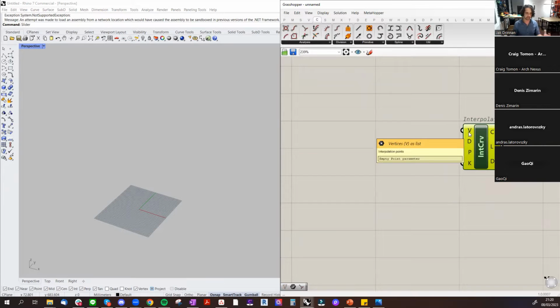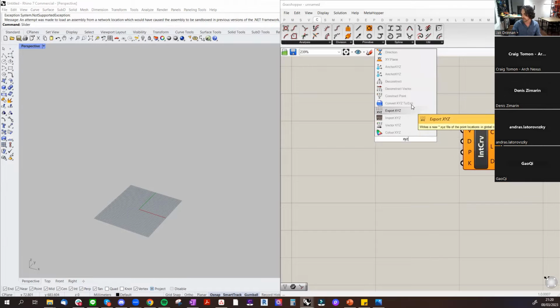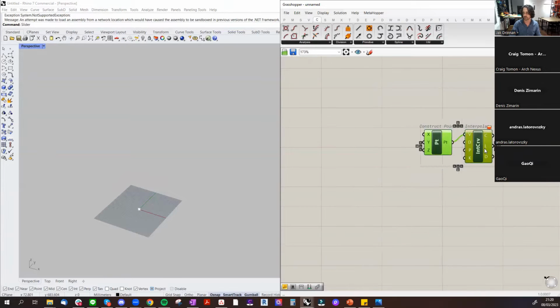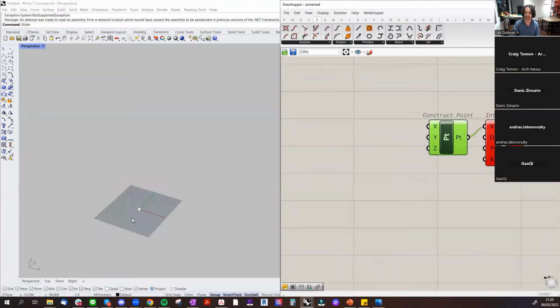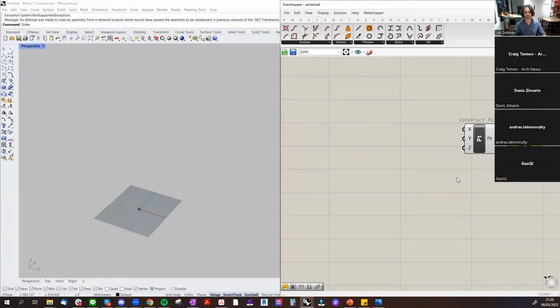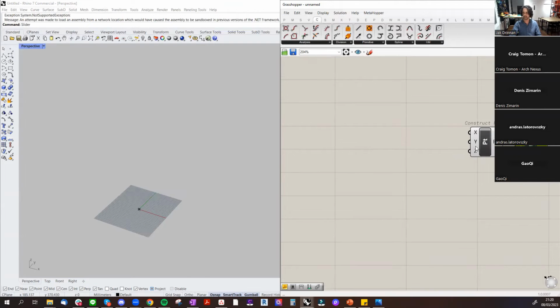The main input really is the first one: what are the points defining this curve? We can answer this question immediately with an XYZ point. That can go into here. Now we get an error because the XYZ point is already outputting a point, since it already has some inputs in here, but you can't draw a curve with just one point. This is why we're getting this red error. So we need to input some information into these X, Y, and Z coordinates.